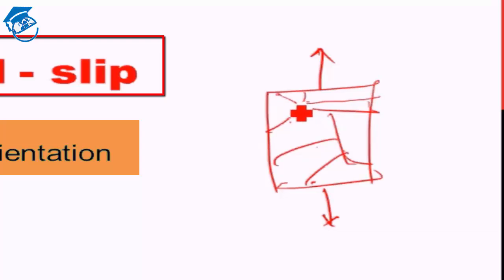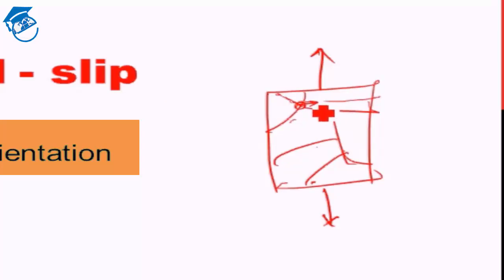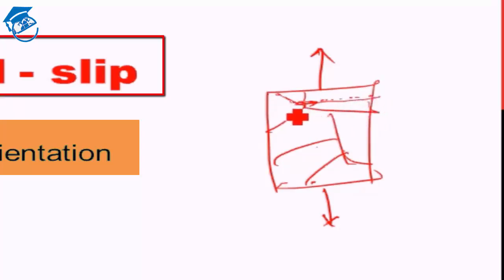Now for the dislocation to move from here to here, sufficient stress needs to develop over here such that either this dislocation which came here breaks through the grain boundary and travels in the next grain, or a sufficient number of dislocations accumulate here so as to generate enough strain to generate new dislocations in the adjacent grain and let those dislocations move further. Right. So here what is happening is, since there is continuous change in the slip system due to the presence of grain boundaries, the dislocations are physically restricted.